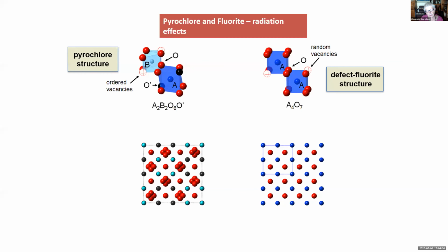People often say that a structure is destabilized by distortions. That is not actually true. A structure may be destabilized as a function of composition, but at a given composition, if the distortion occurs, that distortion occurs because it stabilizes the structure under that constraint of composition, temperature, and pressure. So whereas the material may be destabilized relative to some other composition, the equilibrium degree of distortion gives it the maximum stability. And the purpose of the distortion is indeed to do that.